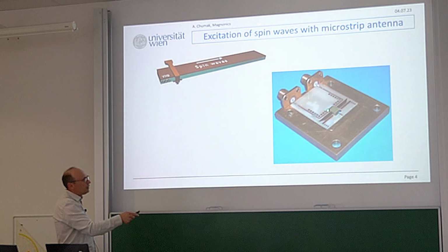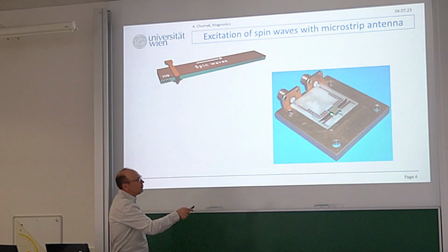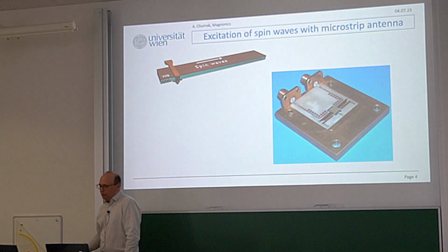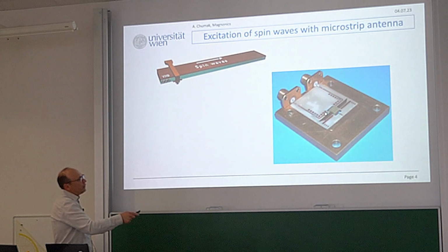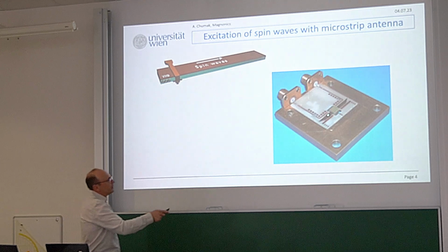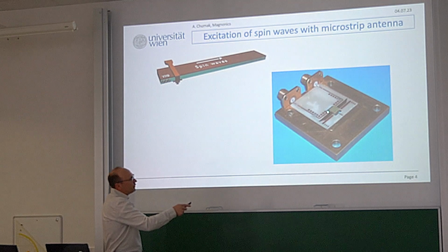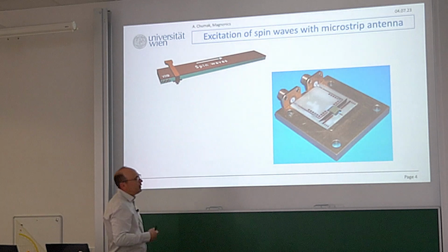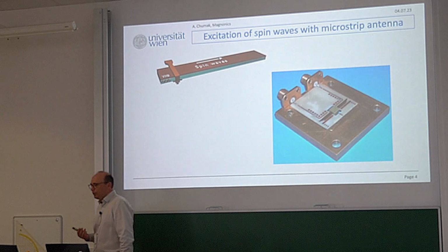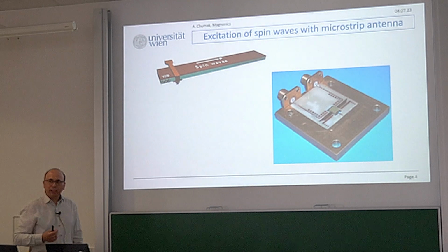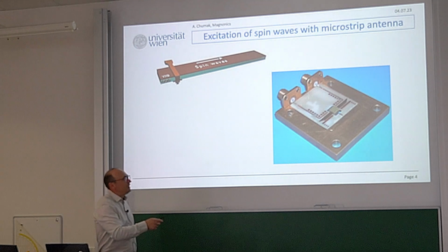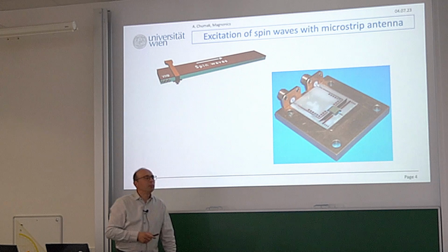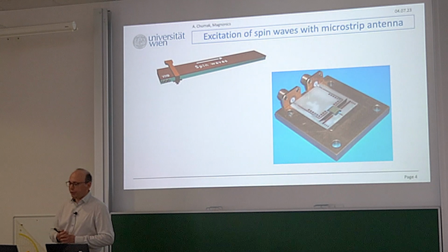The antenna itself stays here, and it's very narrow. Usually we go for something like 50 micron wide, sometimes 25 micron. You can hardly see it, but here it's just such a narrow antenna between these two parts. There is no adapter here. But nowadays we use an adapter, because a 50 micron wide antenna in a microstrip line cannot keep 50 ohm characteristic impedance. It's not CPW, it's a microstrip line, and when you make it very narrow, the characteristic impedance will be different.